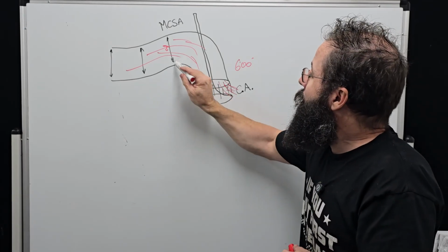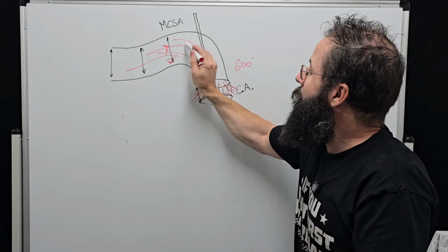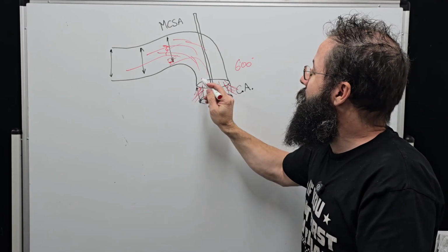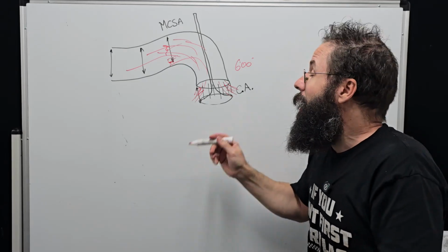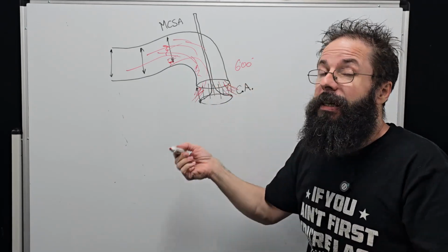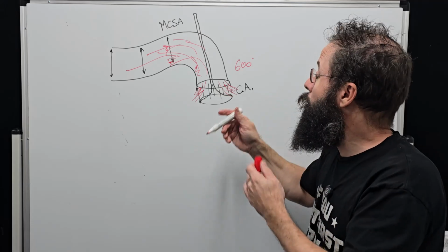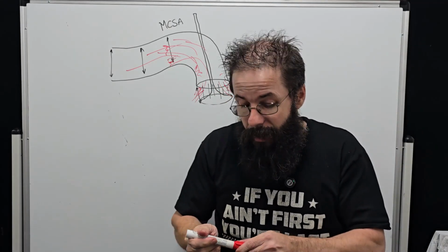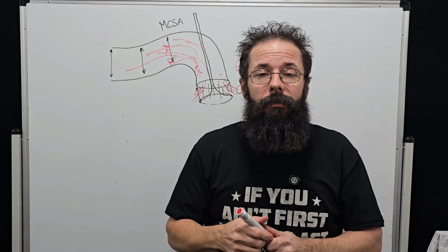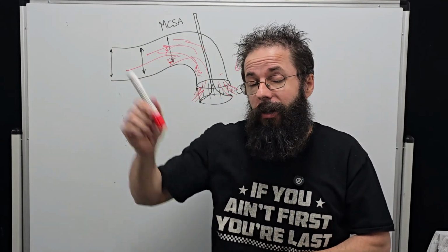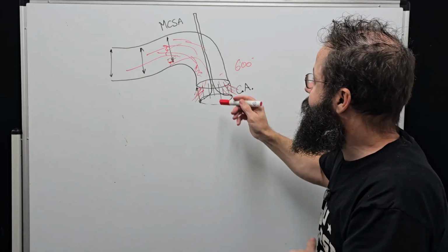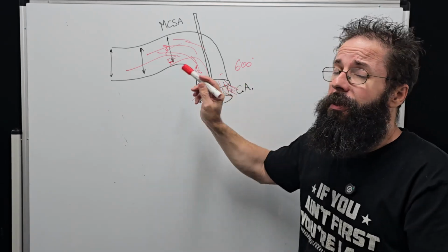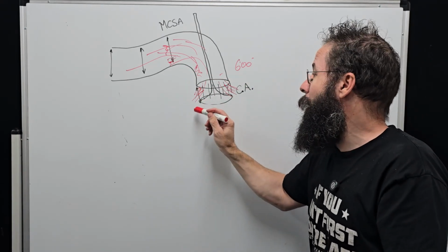And now the high velocity is here, and now the high velocity doesn't want to make the turn anymore. And that's why we hear separation or more turbulence and so on. And we start to lose that cross-sectional area, and you'll see the head nosing off on the flow bench rather than carrying the CFM. And that has to do with the saturation point.